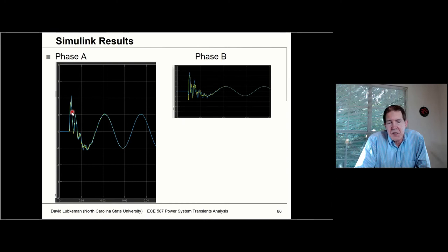And then what you would need to do to damp this out is maybe use surge arresters or some pre-insertion resistor on the switching, or maybe control the time we do the switching in order to keep this receiving end transient from jumping up to such a high value.